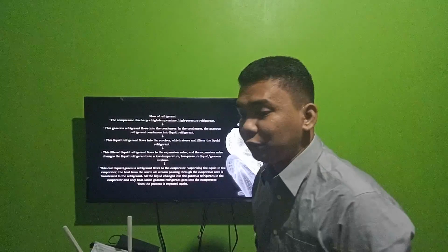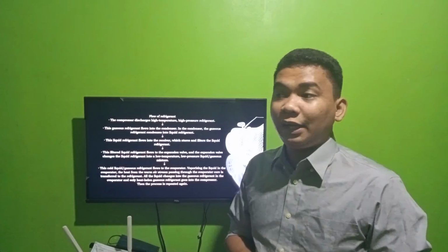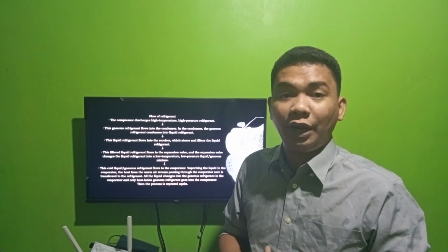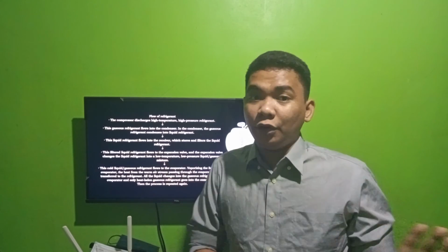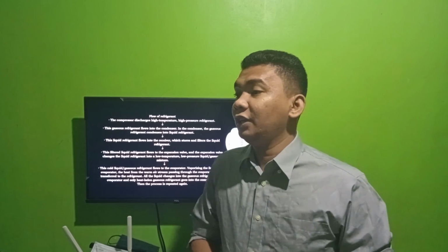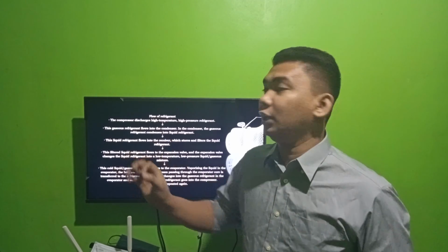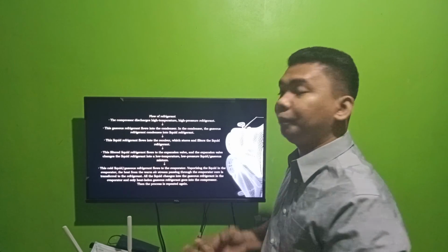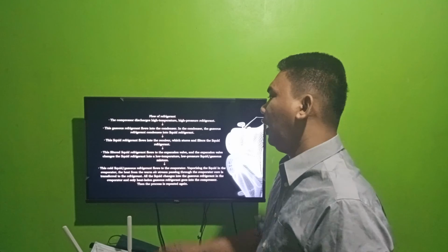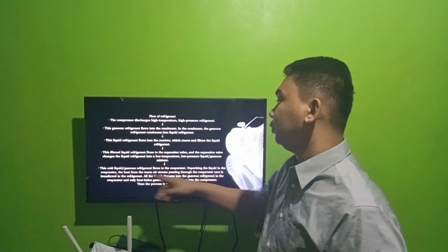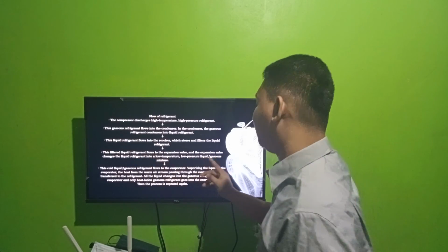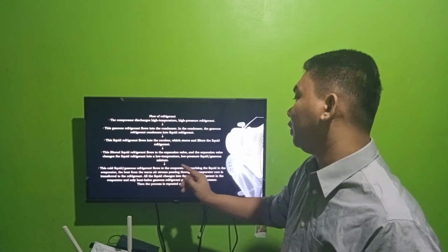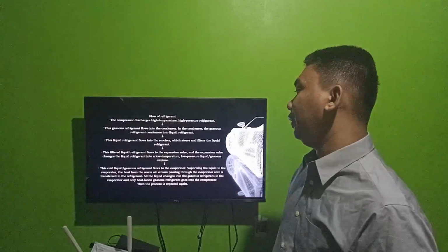Again, the expansion valve has a sensor. It expands when needed, depending on the pressure required. So again, the difference from the orifice tube: the orifice is fixed, it's just a hole. This one varies the pressure and also the amount of refrigerant. So the filtered liquid refrigerant goes through the expansion valve and becomes a low pressure liquid and gaseous mixture. Lastly, this cool liquid and gaseous refrigerant flows to the evaporator, vaporizing the liquid in the evaporator.